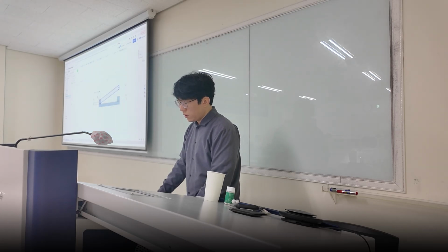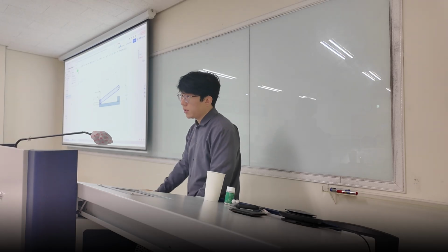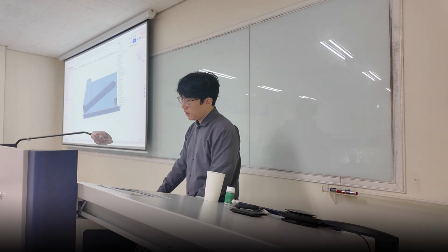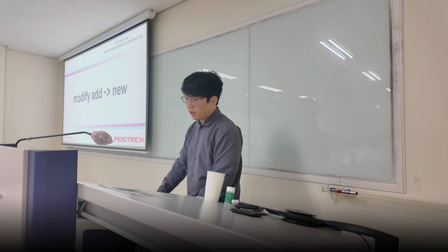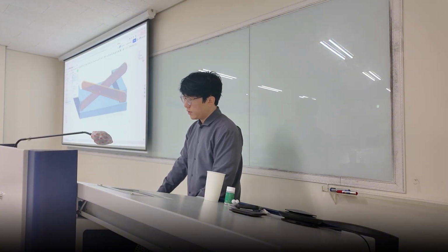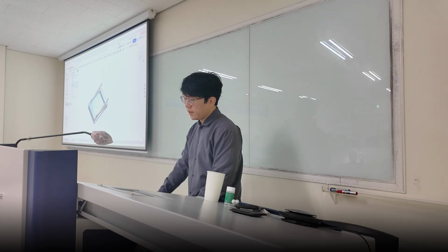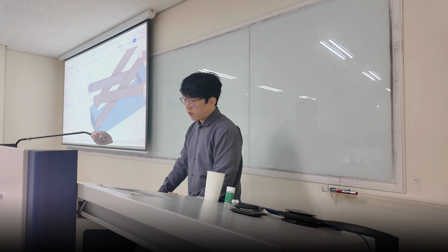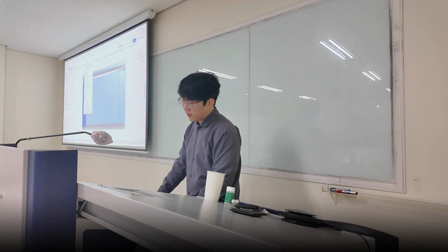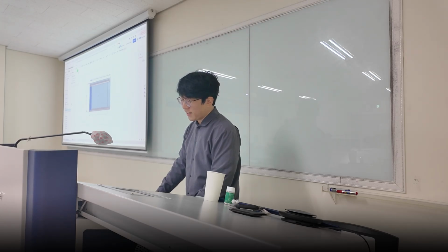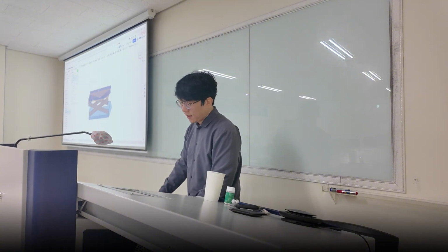So you're gonna draw these lines, of course. Select the radius and length properly, and then draw a new sketch and add a new one. See how these are in different colors again. This one's blue. These are in gray. You're gonna add a new sketch to it, and then make this rectangle fit right between the legs, and then create another sketch.